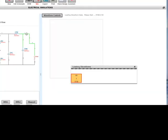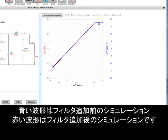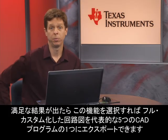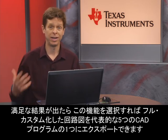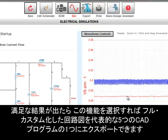Alright, my simulation is complete and I can load the waveforms. So the waveform in blue is the simulation prior to the filter, and the waveform in red is the simulation after the filter. Now, once you're satisfied with the results of your simulation, you can actually export this fully customized schematic into any one of 5 popular CAD programs by selecting this function.